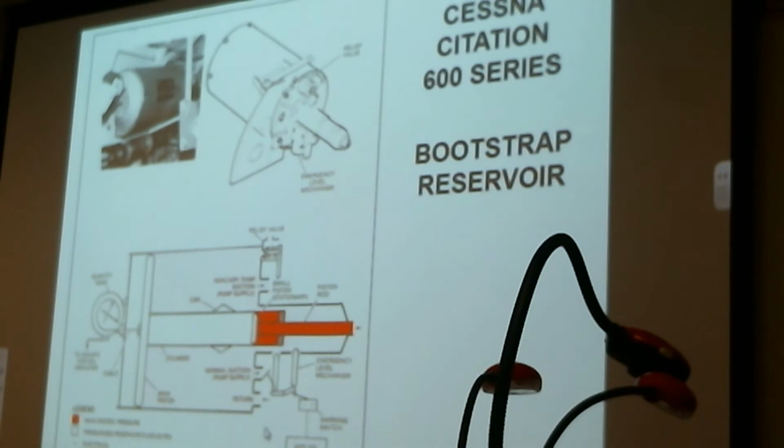Okay. They also have some limit switches as well. There's a cam that's incorporated on the rod of the piston. And what it does is it operates an electrical switch, and it tells me when the reservoir quantity is low. So the piston position is really the indicator for fluid quantity.